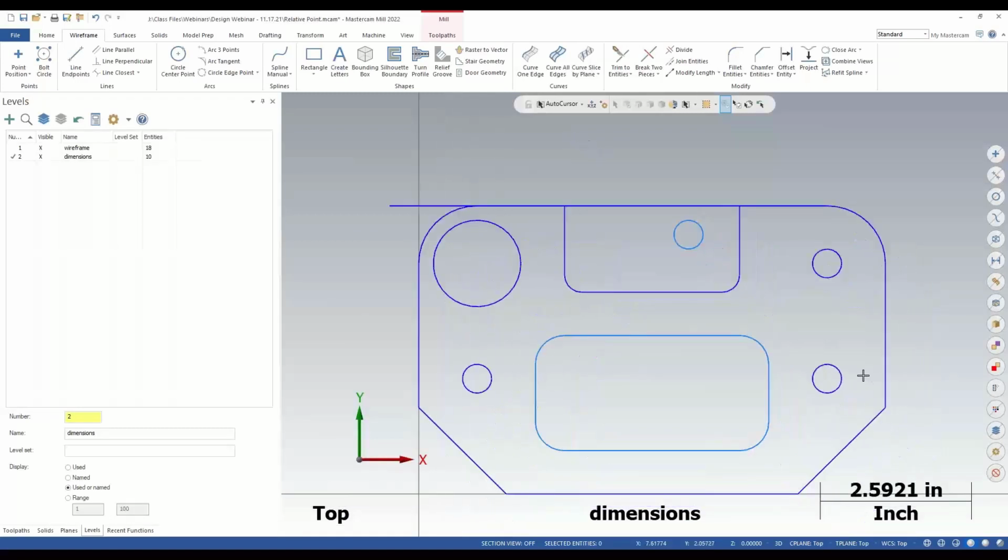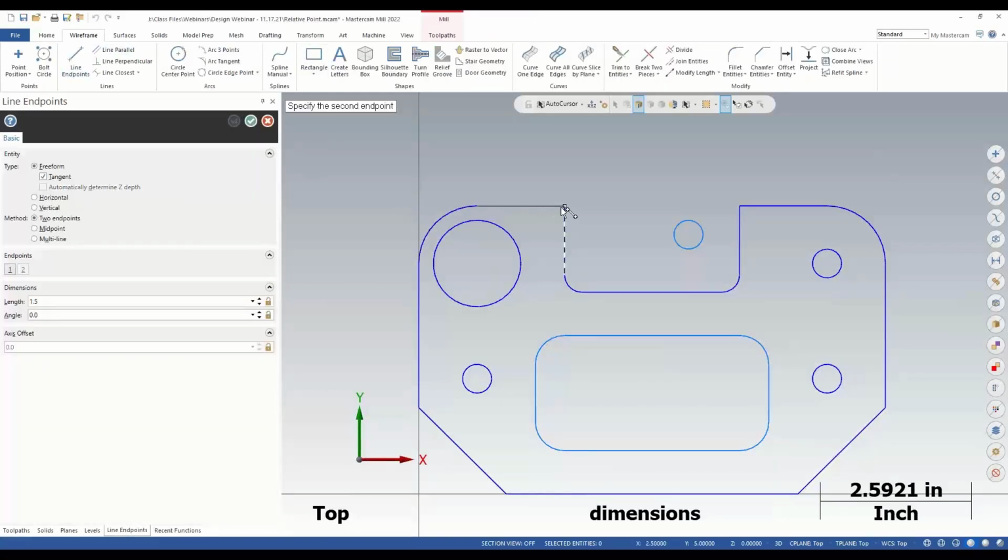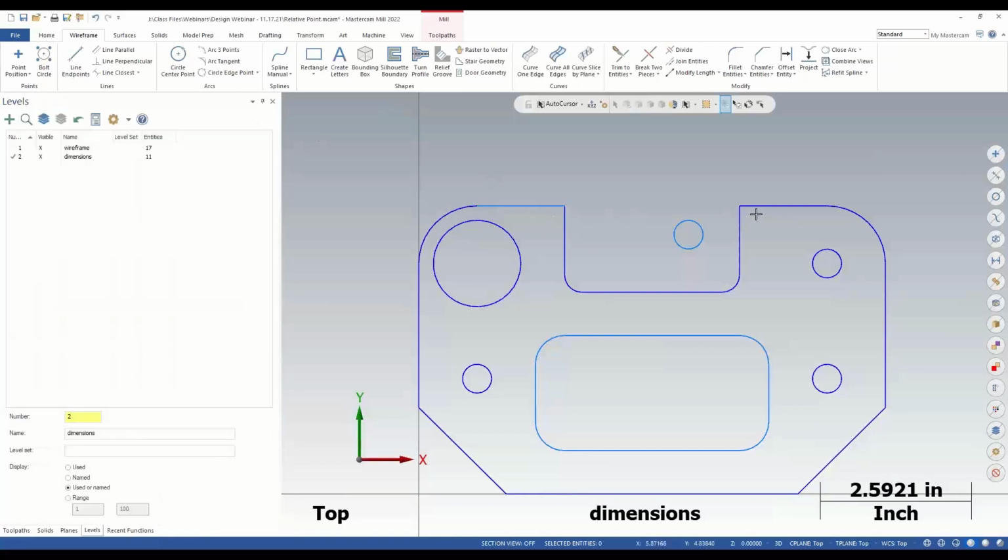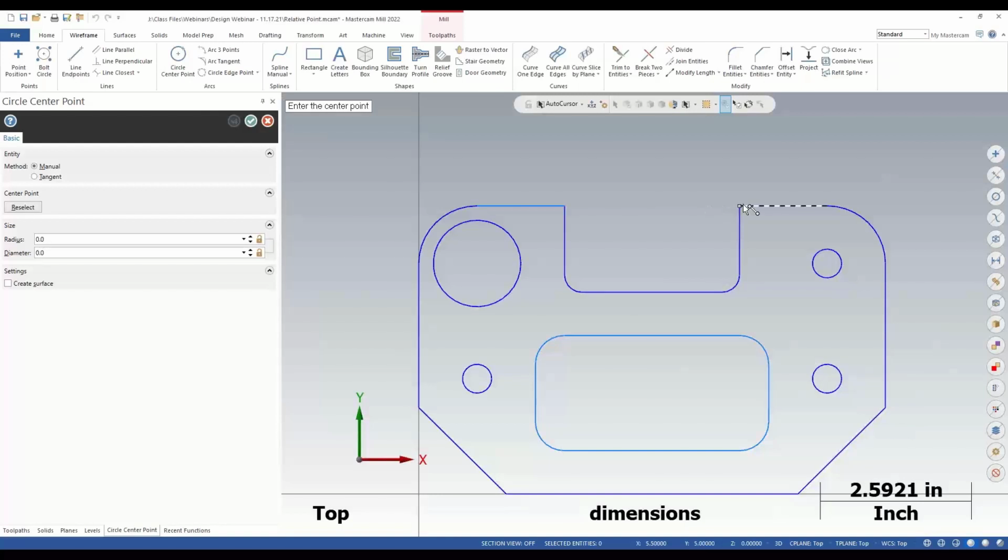Another thing we can do here, I'm just going to real quickly talk about, it's something I try to talk about in class, but sometimes I just don't get a chance to talk about it, and that is what's called temporary midpoint. And now, guys, I've seen a lot of people run into the situation where they're trying to draw something, and let's say they want to draw an arc between this point and this point right here. So I'll use the control key to highlight those. They want to make a point right in here, but between these 2 points in space.